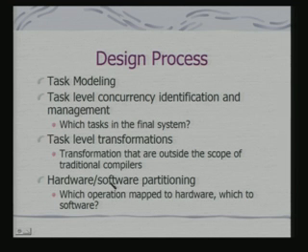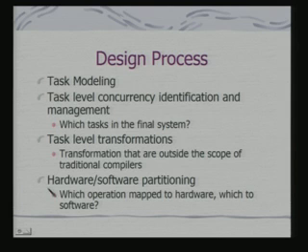That should be followed by the hardware software partitioning. That means till this point we are dealing with the task representation. We are trying to derive an optimal representation of the task. Then we should look at the hardware software partitioning, that is which operation is mapped to hardware, which to software. In fact, when we look at use of automated tools, many of these transformations and the partitioning aspects can be put together and combined as part of facilities provided by the tool.